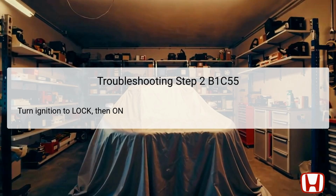The vehicle's computer utilizes this opportunity to run its self-checks, which can confirm whether the DTC B1C55 will reappear after this reset. Following this step, it is important to proceed with monitoring the vehicle for signs of DTC reappearance before moving on to the next steps in the troubleshooting process.